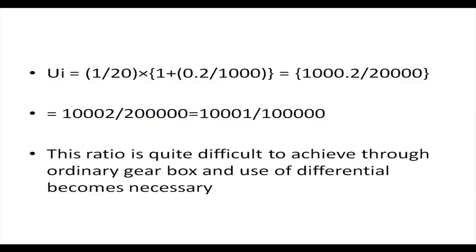Instead of that, if you employ the differential system, that means there will be lead change gears and the differential, the problem of achieving a particular number of teeth and the problem of achieving a particular helix angle become totally different. They don't remain an integrated problem, they become mutually exclusive. So, this is the reason, to avoid such difficult gear ratios, we finally go for the differential instead of a no differential system.